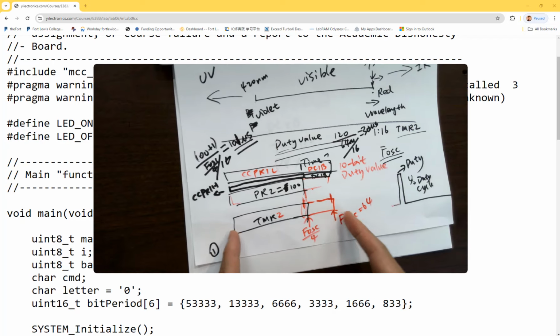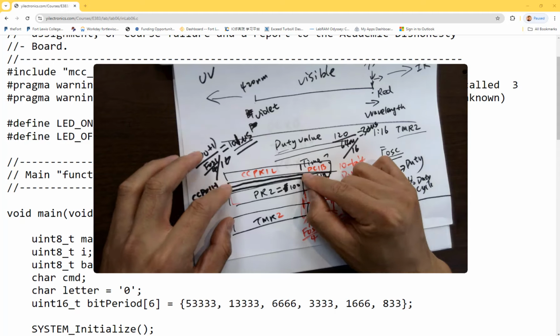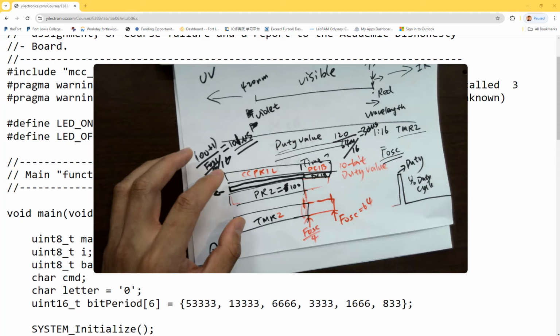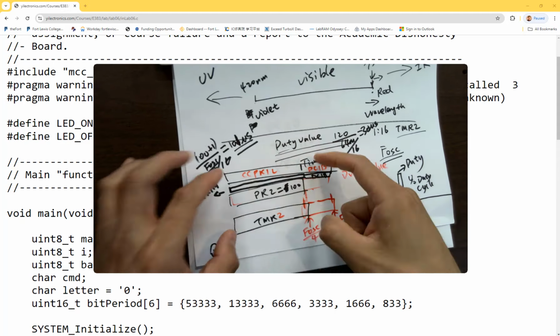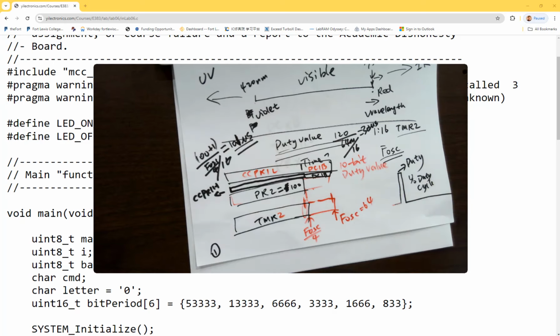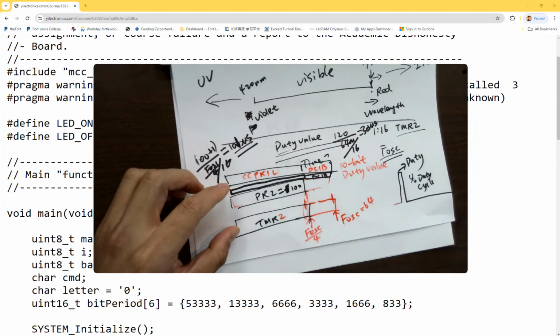Why it's designed that way, that's probably one more cycle taken here, and that's probably why you have to add 1 to PRx. I don't know yet, but it's very likely because whenever PR2 reaches, you have to wait for another cycle to latch it. So it's adding 1 more cycle to the period, not to the duty.